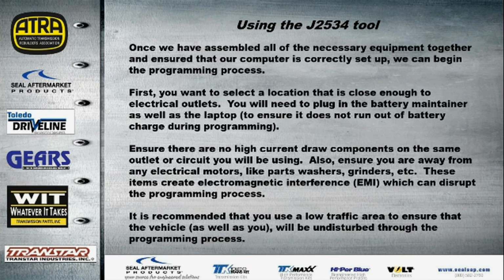Once we've assembled the necessary equipment and ensured that our computer is correctly set up, we can begin using our J2534 tool. First, we want to select the location. We want a low traffic, low noise location. This is something where we can't park it and try to move it, or have the risk of somebody hopping in it and pushing the brake pedal during programming in an attempt to move it. So you want this to go undisturbed. For the most part, that's job number one.